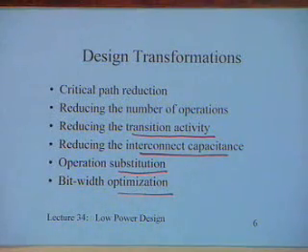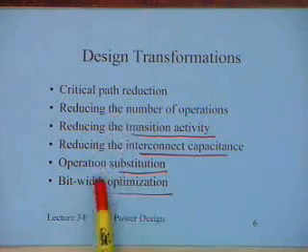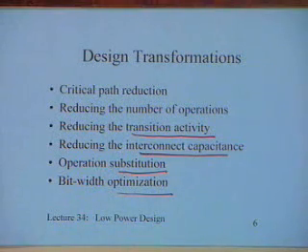At the architectural level there are also certain things that are done which I have not put in over here, because they are now very well understood. If the design is not to be continuously used, for example in mobile applications, you have a cell phone, you are not using it all the time. So there is something called a sleep mode. The sleep mode is a mode in which a minimal part of the circuit is operational, but that part is sufficient to initiate or trigger the start of the application.